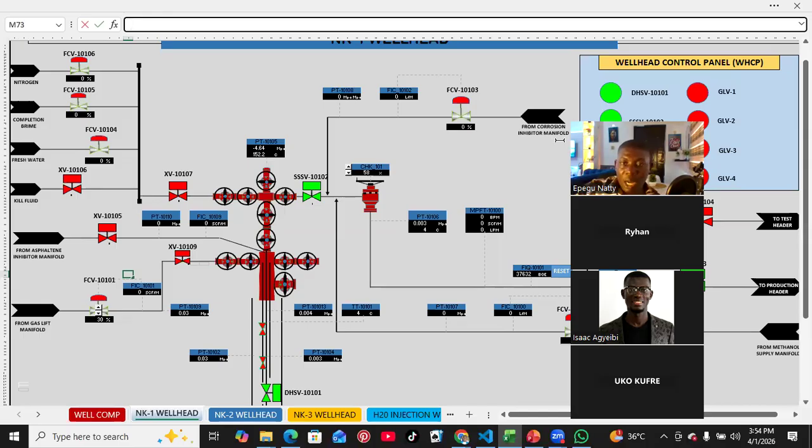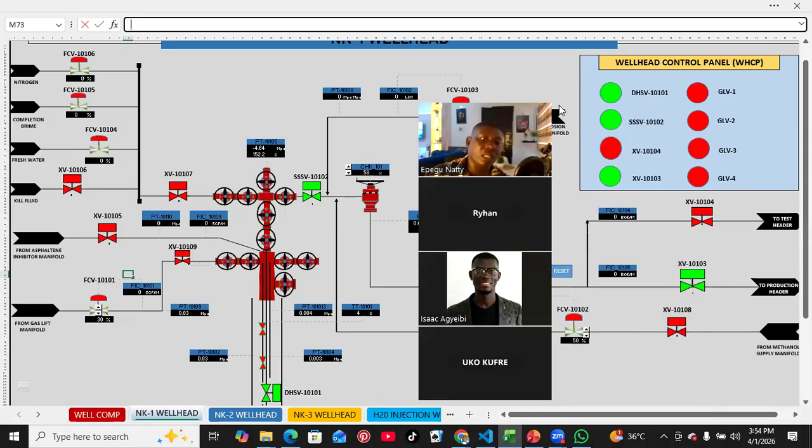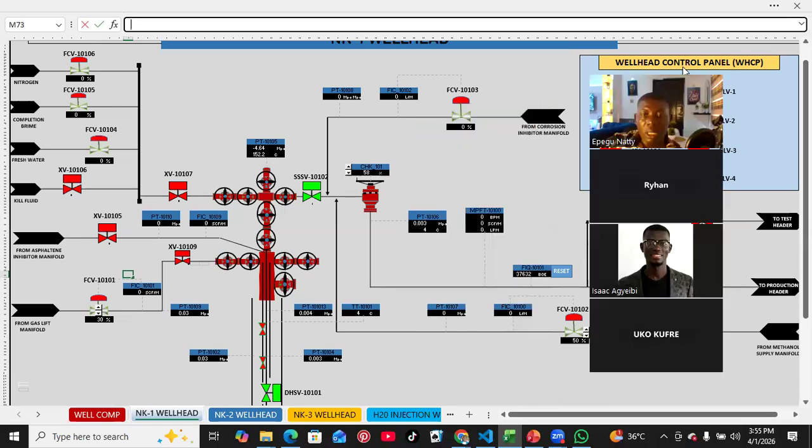For the process line, we have demulsifiers. Those are injected at the separators and also at the dehydrators. But we have the methanol injected at the shock valve, just after the wellhead, before the manifold. The corrosion inhibitor is also best injected before the shock valve.